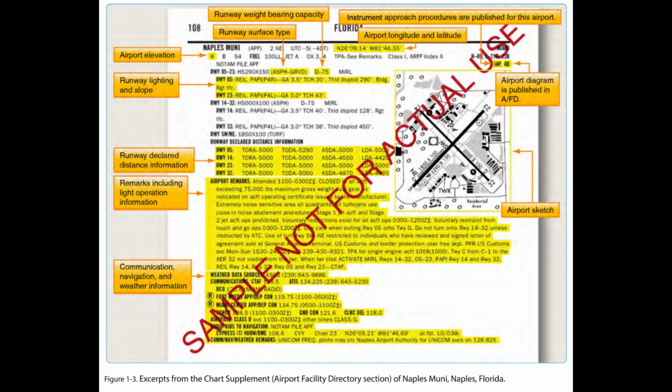Part 91 operators are expected to comply with the guidelines listed in AC 120-57 and should expect follow-me service when available when low visibility operations are in use. Any SMGCS outage that would adversely affect operations at the airport is issued as a notice to airmen, NOTAM.